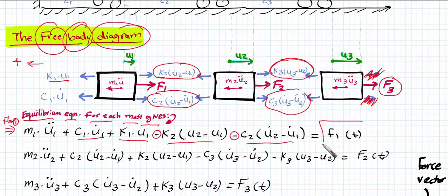And it's a common practice to put the force on the right hand side. Why do we arrange them in this way? Because it is going to be easier and more informative when we deal with it mathematically. Then we find that our equation of motion, or this differential equation, has the applied force on the right hand side, and the left hand side has the derivatives of the main response parameter that we are seeking, which is u.